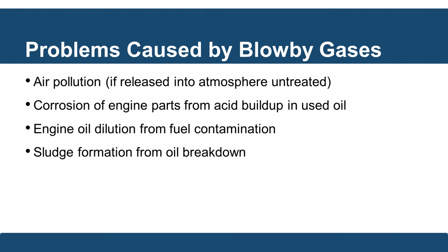That air pollution is released into the atmosphere if it's not treated, and this also leads to the corrosion of engine parts from the acid buildup that's in the used oil. We still get it in there, and that's why we have to do oil changes. The engine oil dilution happens from the fuel contamination in that mixture that blows by those piston rings, and then we end up with a sludge formation once that oil starts to break down.